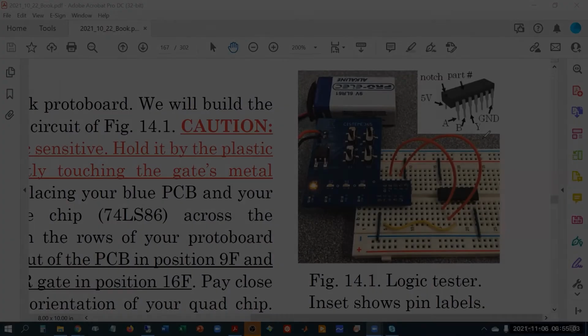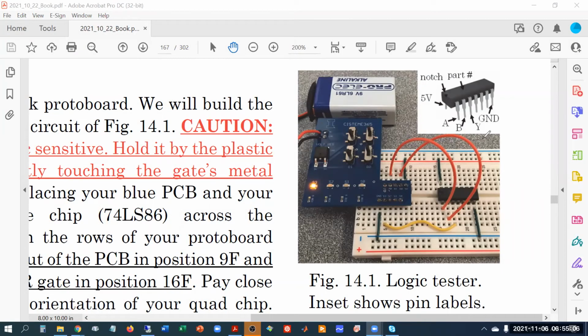Some of the other issues that people face when they're testing the LED calculator, and why sometimes they have errors, has to do with these pins. When you're inserting these pins into the breadboard, sometimes not all of the pins will plug in directly. Some of them will get bent underneath and won't make contact. Sometimes they get bent outwards. So when you plug it in, be very, very careful and make sure all the pins plug in. These are thinner than the normal wires, so it's very easy for some of them to not plug in.